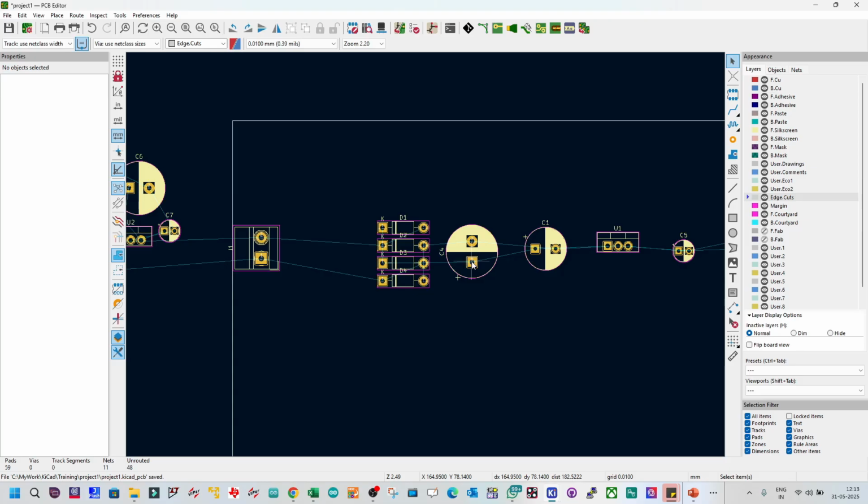It's all a trade-off. If a jumper will solve the problem, let us have a jumper. But if you are trying to not have a jumper, and still trying to manage the routing with crisscross routing, this is going to mess up your layout, which is not good. The layout should be very strong and clean.